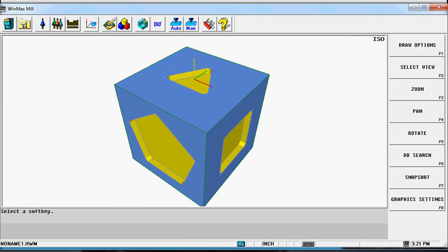Now I would just continue to do this same transform plane, milling blocks, whatever features I need to do, transform plane end. Transform plane, new 3-axis milling blocks, transform plane end. I would continue to do this until everything on the part was machined as I needed it to based on the print that I'm trying to machine.